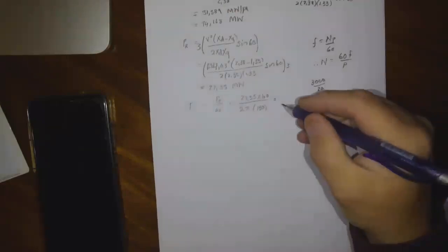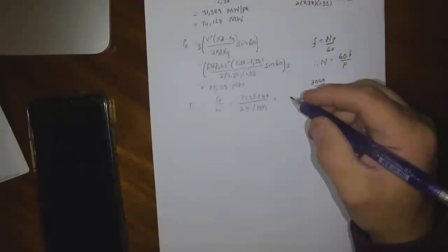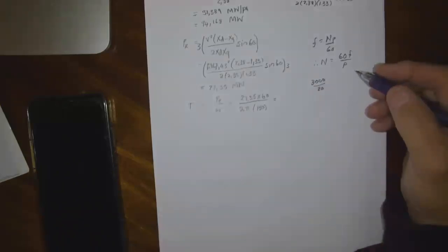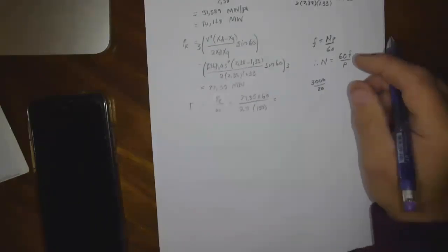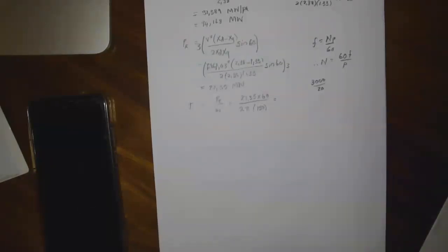Oh, okay. Before you continue on that one, you see that reluctance torque is responsible for running our alternator when we don't have E. Even if E is 0, the alternator will still turn because of that reluctance torque. But it won't start. It doesn't start, but it will just run, if the reluctance torque is bigger than our losses. If it's less than that, then it'll stop.